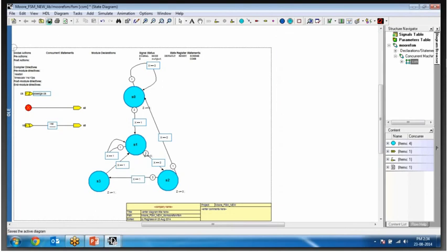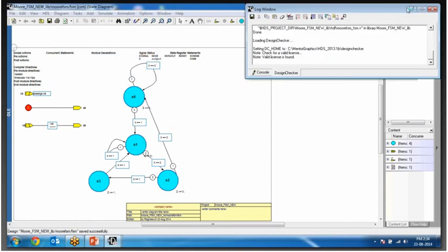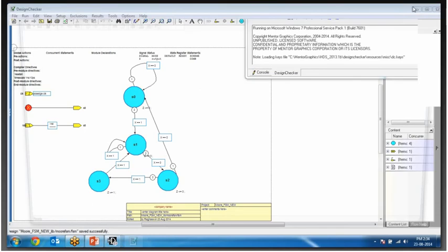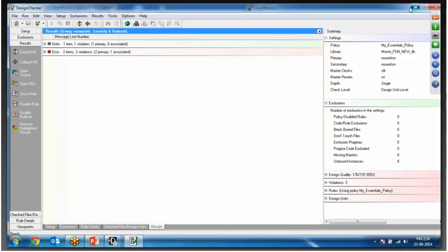Now click on save. So now we have this complete condition. Our FSM is ready to find a pattern of 101. I have just saved and I'll quickly run the design checker flow. Here we are not having any errors and warnings. I'll just minimize this.